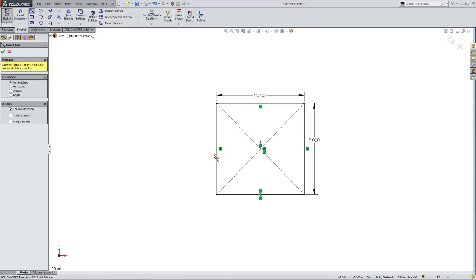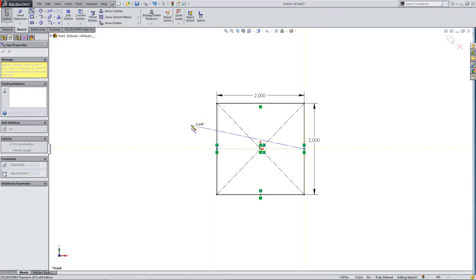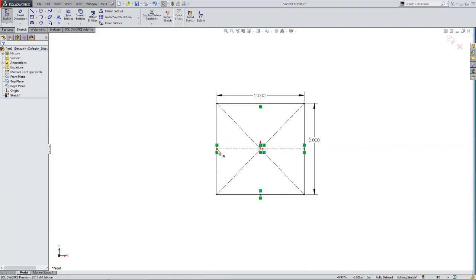You can use a center line, and if we wanted to use center lines instead, those endpoints can be used as pierce points. And for symmetry's sake, we can put another point here on the top. So each of these midpoint pierce points can be used. The origin will be the default pierce point, and we've also got the corners. Just make sure that anywhere you might use as a pierce point is located on your profile.